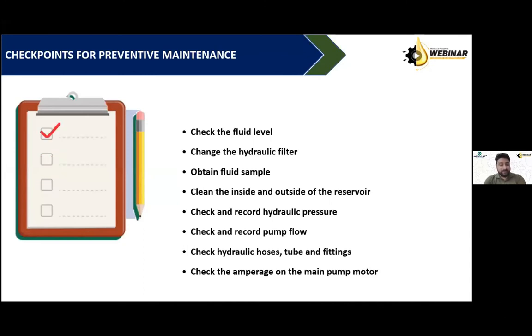So changing the filters should not be a burden for you. It should rather be a happy activity, because if the filters have got clogged, you must have a feeling that, yay, I got my contamination trapped in the filters, and the contamination which has choked my filter is not present in my system anymore. So you should actually feel good about it and not find a headache in changing the filters. Obtain the fluid sample properly and send it out for testing, either in your lab or in the